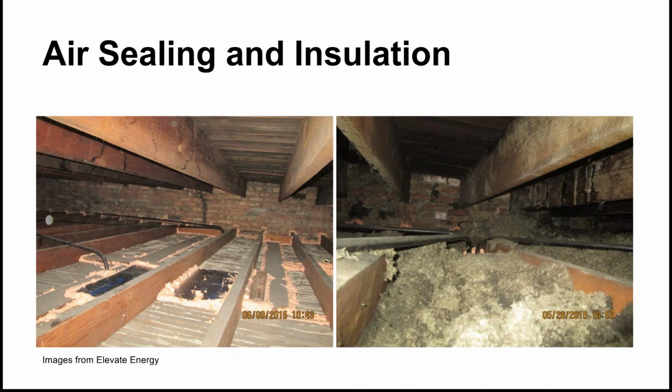You might know that insulation is measured in what's called R values, or thermal resistance. One important thing to consider here is that insulation must be continuous to ensure a maximum R value. If you have maybe half of your wall insulated, the heat will flow through the easiest path, which will be the completely empty space.